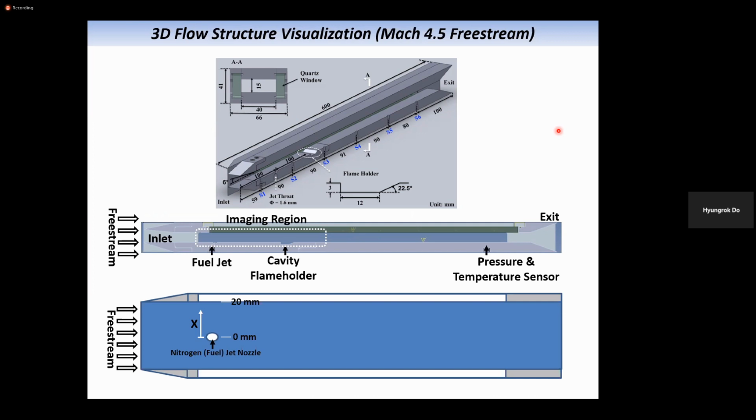But if you are using deep IR or mid IR wavelengths of several micrometers, then a fused silica or quartz window is not transparent to that wavelength. So you should use sapphire glass. It is much more expensive. But anyway, depending on the light source or the laser diagnostics you are going to use, your access window should be different.